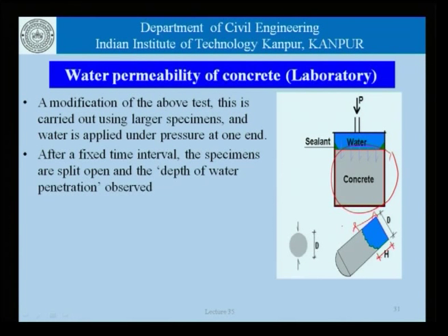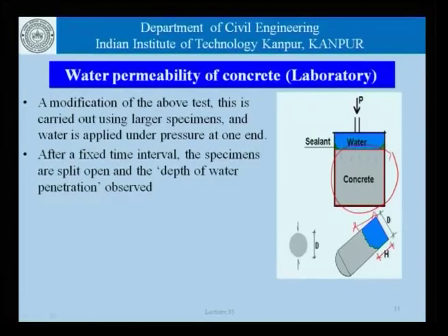And this depth of penetration of water again is not so easy to measure because of reasons arising from practical considerations, in terms of the presence of aggregates, the non-regularity of the pore structure, and so on. At times, if the sealing here at the edges is not very properly done, it is likely that the water can move along the edges and penetrate into the concrete from the sides, in which case instead of getting a profile like the one that is shown here, we may get a profile which is something like this, with water coming from the sides, and that is highly undesirable as far as this test is concerned.